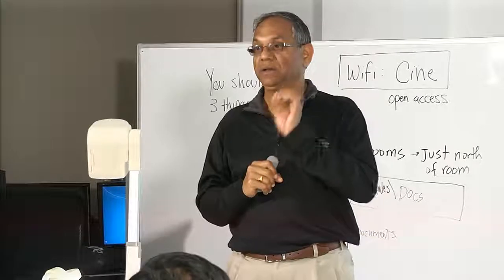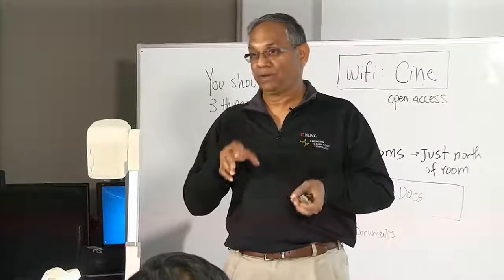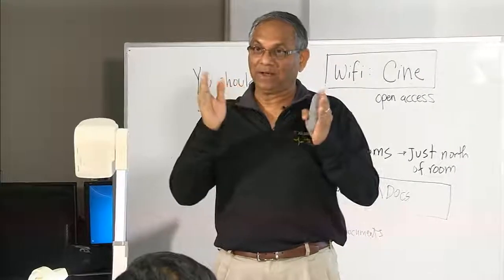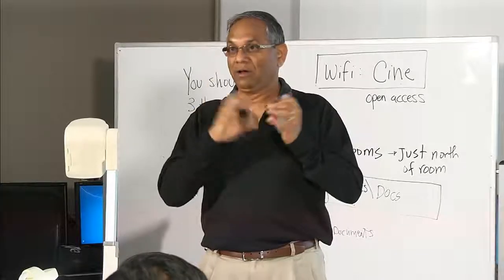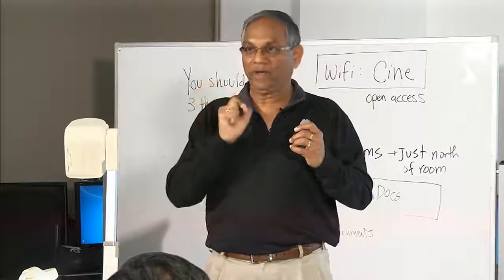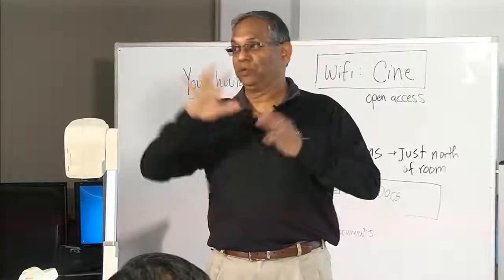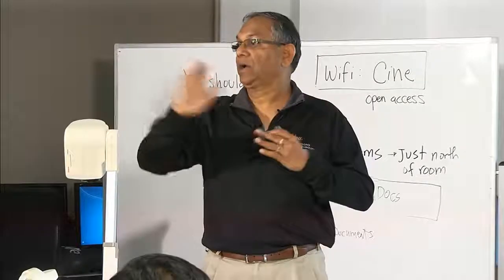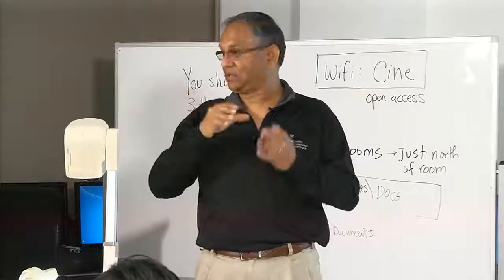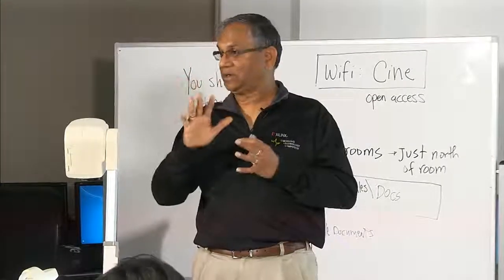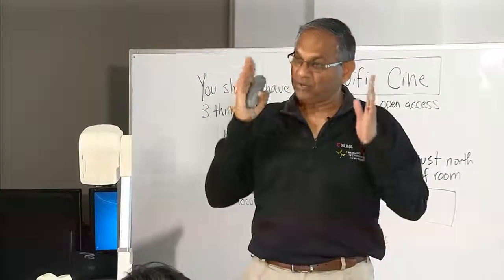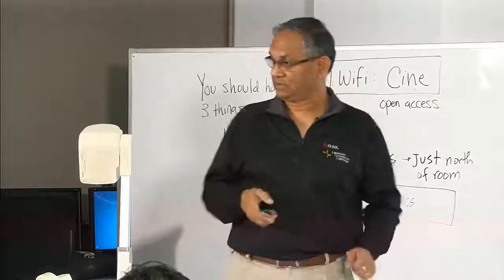Because of the programmable interconnect. If you write the model and you characterize it and say this path can run at 100 megahertz, and you have several logic levels, so it's going through a combinational path, then if you make some modification, it may do a different place and route, and your timing can be totally off. You don't even have to add another logic level. Just re-implementation of the model can mess it up. So always in FPGAs you deal with clocking edges, synchronous design.